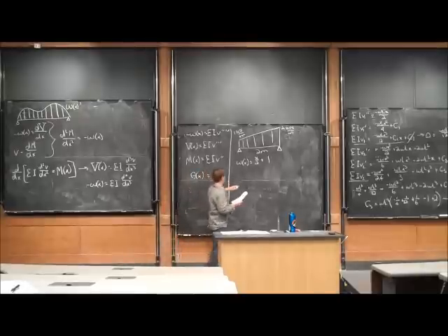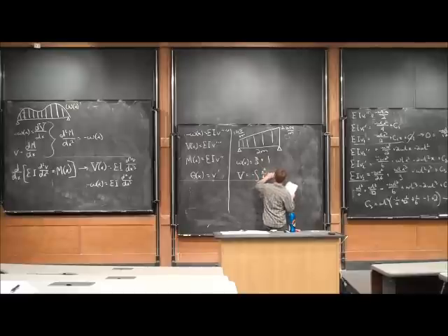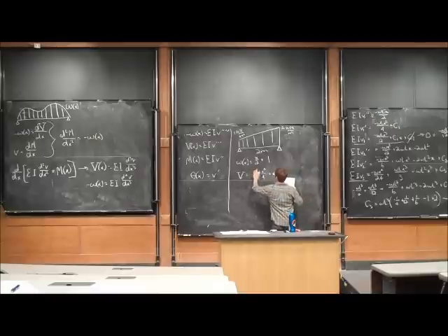So I can integrate this to get my shear function. My shear function, which is equal to the negative integral of that, is then equal to negative x squared over 4 plus x. Oh, I already integrated it. So negative x squared over 4 minus x plus c1.